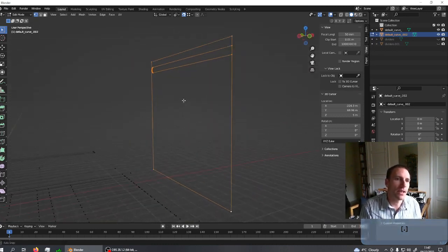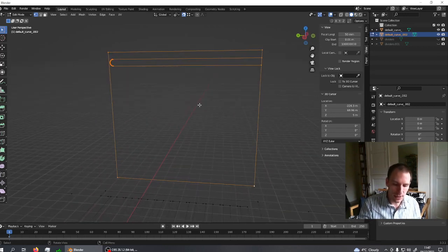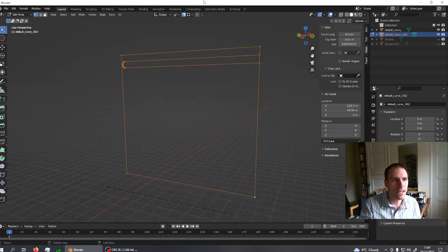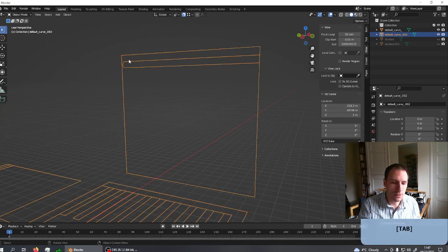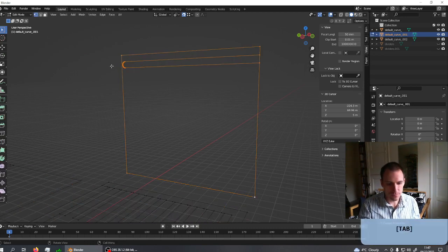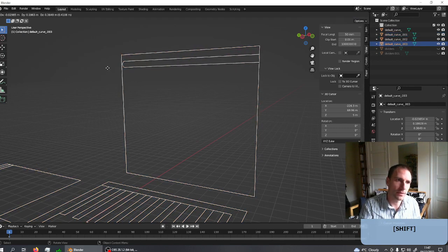Now this is a piece with a slot cut into it. So what I can do is make this and boolean it out again. This is something that I've designed to do with a router, as you can see. I used to make this in wood, but I can't be bothered. So if we go back into object mode and Shift D, escape, it puts it in the default place. Right. In fact, let's duplicate that twice so that I've got a reference drawing.